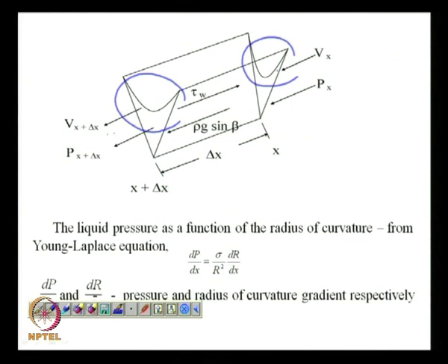There would be flow from the cold side to the hot side, and I have a body force, and since there is flow from the right to the left, the shear stress acts in the opposite direction, and at the same time, since you have a difference in curvature, that is going to give rise to an additional pressure gradient in the system.